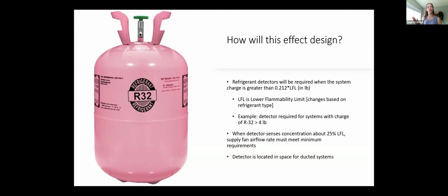And for the R454B equipment, the allowable refrigerant charge is smaller. So I wish I had rules of thumb that said you could provide this system and you won't have to provide detection. But I believe most systems and most building types will require detection unless you put an air-cooled chiller outside your building or use direct evaporative cooling.